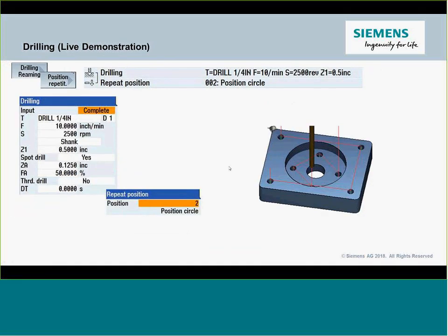we're now going to finish our holes. So we're going to come in. Now, in the lower holes, I don't have as much material to go through, so I'm just going to use the drill reaming function. And that's going to be a scenario where it's going to feed to depth and then pull out of the hole. So the drill option feeds to depth, rapids out of the hole. The reaming portion feeds to depth and feeds back out of the hole.